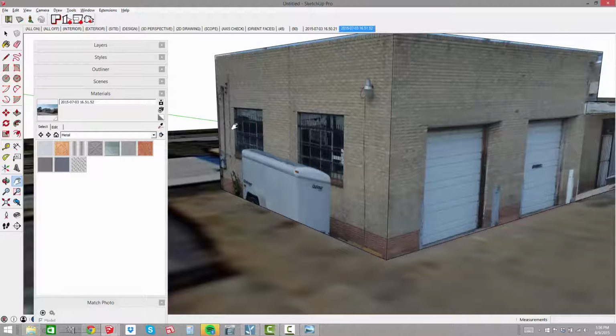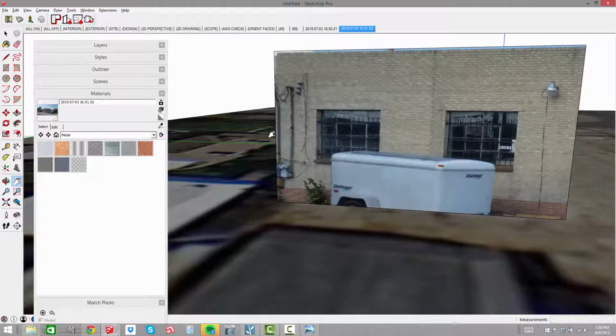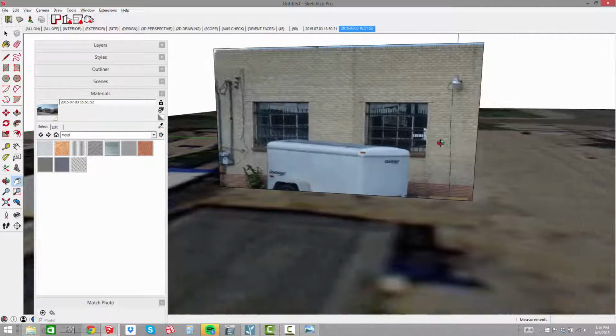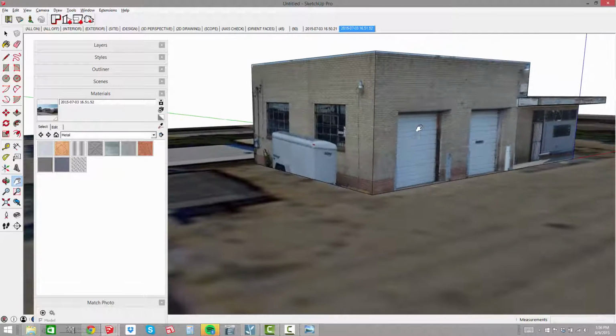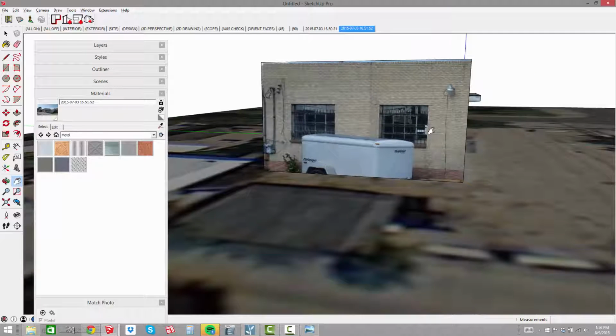We don't need to have wires hanging down and all the utilities plugging in. So let's see. First things first, I see two opportunities for components. Whenever we create components, that's for repeating elements, similar elements, and lines of symmetry. In this case, we've got 2 repeating garage doors and 2 repeating windows.